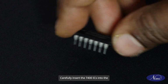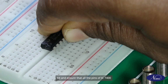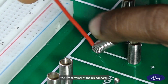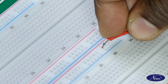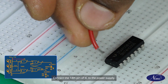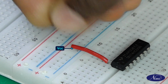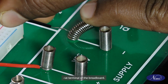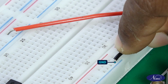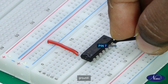Carefully insert the 7400 IC into the breadboard located in the digital IC trainer kit and ensure that all the pins are aligned properly. Connect the plus 5 volt supply of the trainer kit to the positive terminal of the breadboard. Connect the 14th pin of the IC to the power supply. Connect the ground of the trainer kit to the negative terminal of the breadboard. Also connect the 7th pin of the IC 7400 with ground.